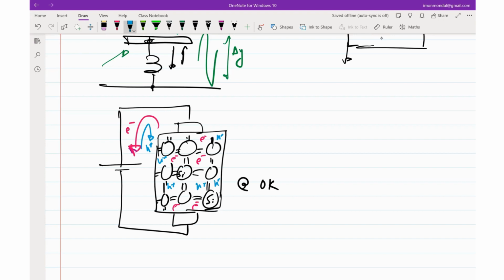But if we peel down one more layer, we understand that whenever we apply an electric field, maybe there is a bond neighboring a hole which breaks, and the electron from that bond fills up this hole, which essentially means that a vacancy has moved. Under the influence of the electric field, since the vacancy is moving, we say the vacancy has moved, even though it is due to the movement of an electron from a neighboring fulfilled bond to a vacant bond. We can model that as a hole movement instead of thinking that every time a new bond breaks and fills up a hole, we can simply say the hole moves.